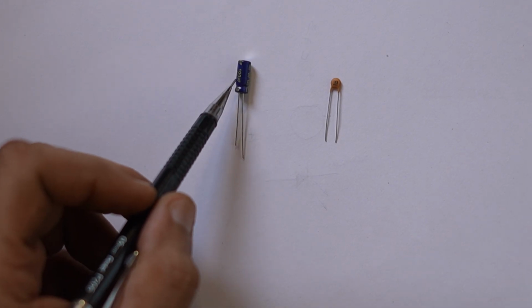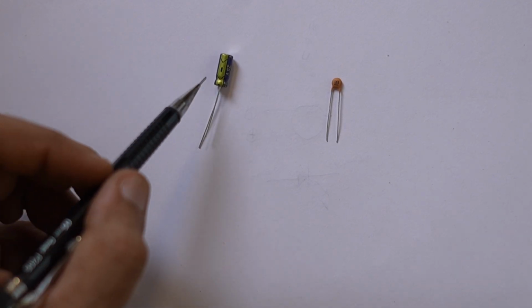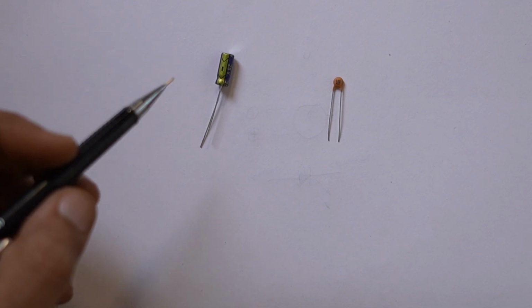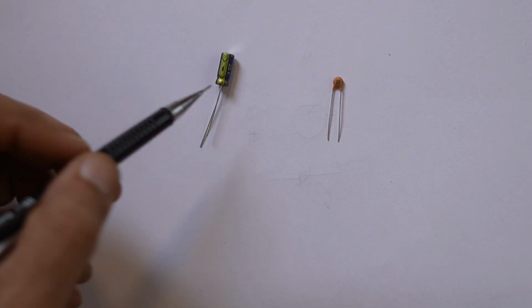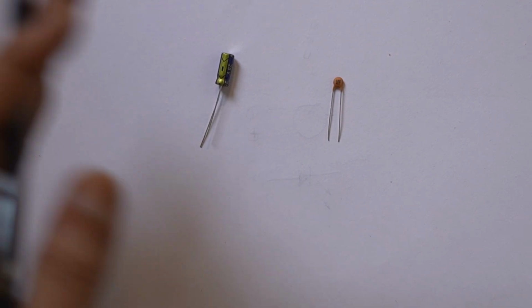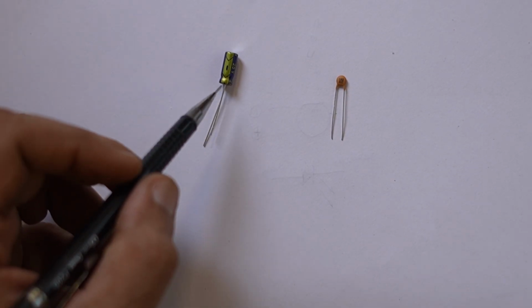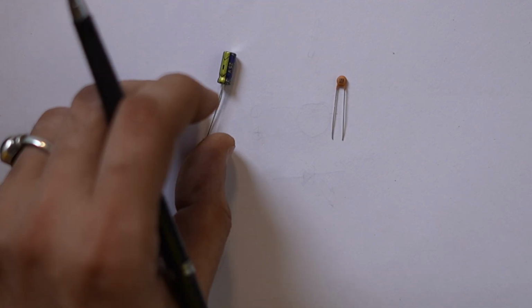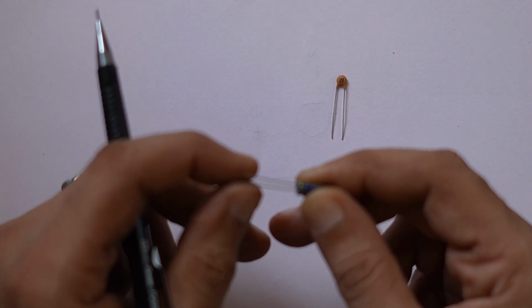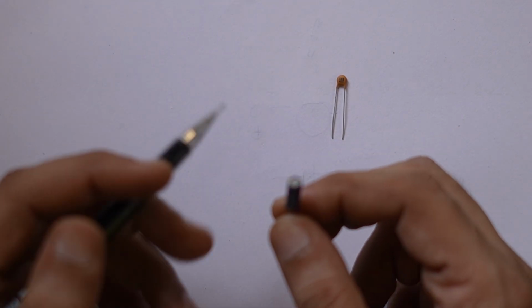The larger ones look like this kind of a can, and if you look at it, it has polarity, just like you looked at the LED, which has a positive and a negative polarity. These are known as electrolytic capacitors, and there are again a wide range of polarized capacitors. These ones are one kind. They will have the negative terminal marked. Again, just like in the LED, the negative terminal is short, the positive terminal is longer, and they come in all sorts of sizes and shapes dependent on two things.